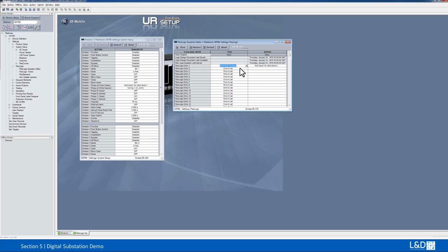Okay, so this is the GOOSE Boolean. The first one is a GOOSE status. So then I choose a NOT gate, and then assign into the virtual output, by using default virtual output 1. So save this one. So that means that we've got the opposite of this Boolean input 1 as the breaker opens.